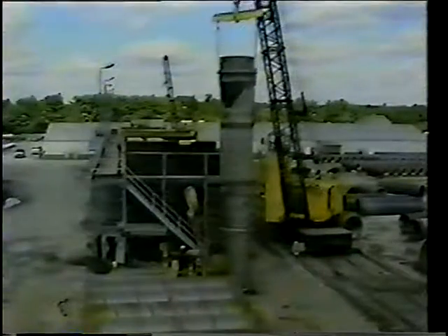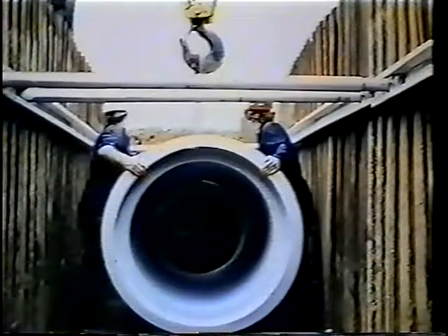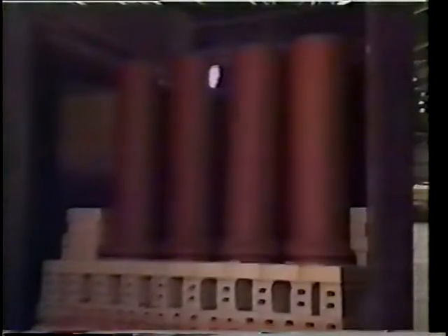Concrete pipe reinforced with steel to carry tensile loads are used for low pressure and non-pressure applications. Pre-stressed concrete cylinder pipe are used for pressure applications. The concrete cores are wrapped with pre-stressing wire under high tensile stress and coated with cement slurry and Portland cement mortar. Non-reinforced concrete and clay pipe are used for non-pressure applications.